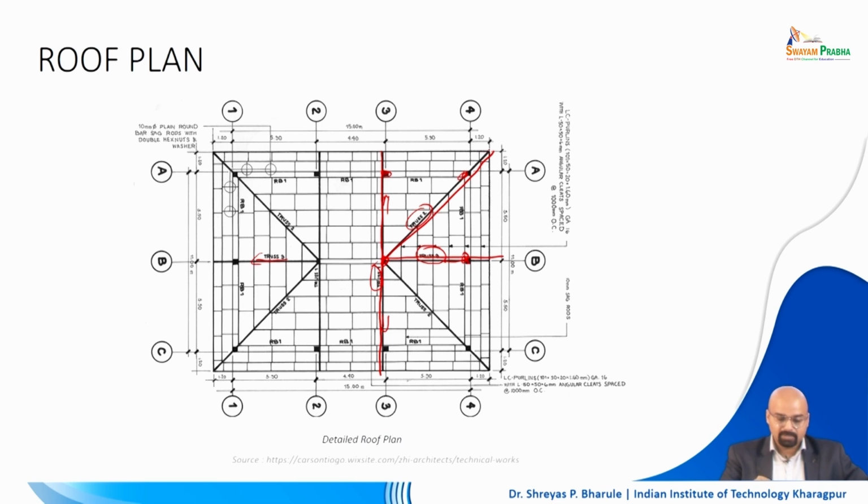So, to have those eaves and to have that gutter at the end of it, you require a sloping, you require to have this kind of a representation. Again, in a detailed floor level plan like this, you need to have the column center lines represented, you need to have the complete dimensioning, you need to represent the distance from where the eave is located from the column center line. How much is the distance between the end of the roof and the column center line, that is also to be represented on both sides, right.